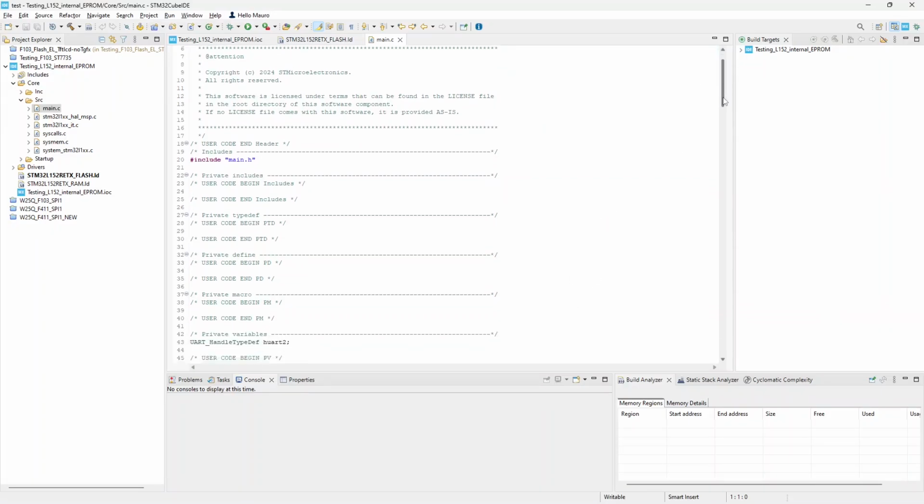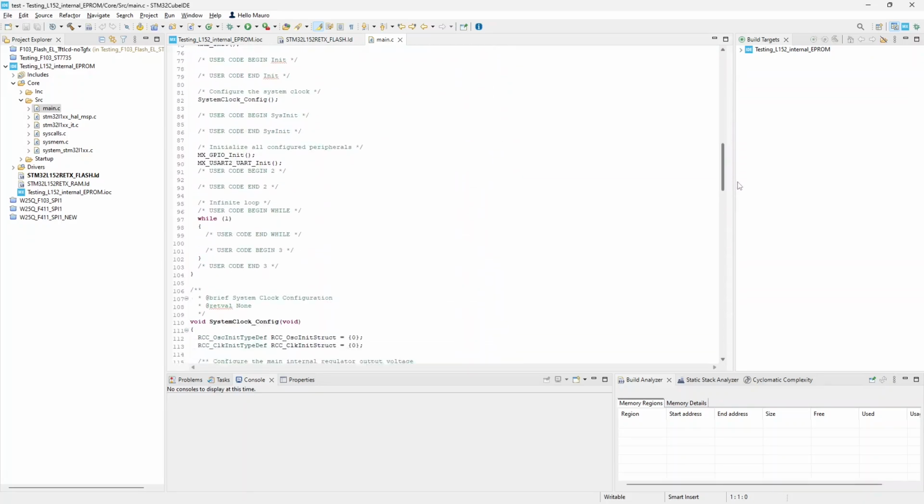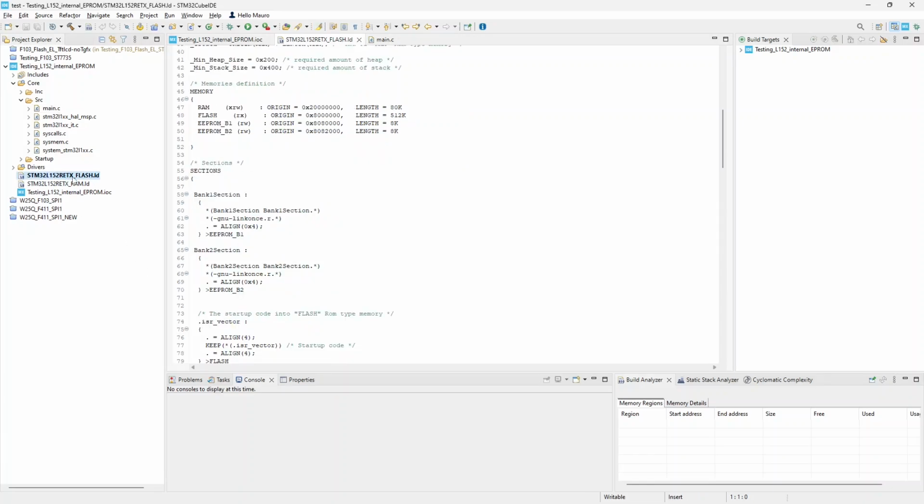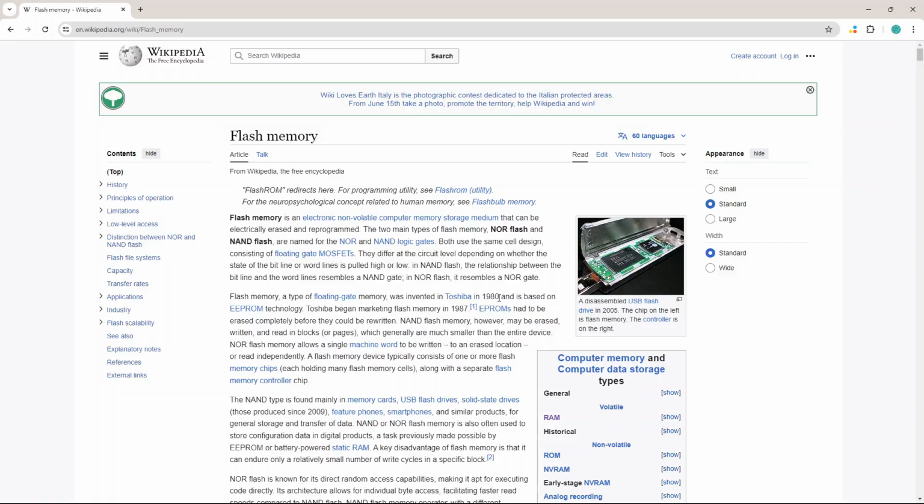Think for instance even just about the program we register on a microcontroller memory, programming it. We want to keep it safe powering off a microcontroller. Otherwise, we should program the STM32 any time we turn it on. That's the reason why a microcontroller is provided also with a flash memory module. That's another type of memory. It is slower than RAM, extremely slower in erasing and writing information into, but keeping data when it is powered off.